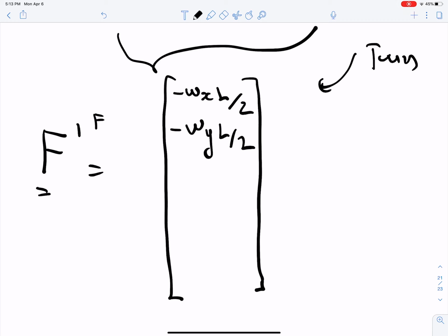Then you went to the ends, found what the equivalent forces are at the ends, and you get the same result. It's just Wx swapped for Wy. So what we're doing now, we take in the oblique load, and we simultaneously account for the vertical action and for the axial action. So we're combining the developments we did for the truss and for the beam column.